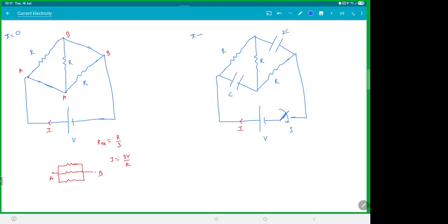If you wait till infinity, the capacitors will get full. Now be careful. There is a charge there. I don't know how much, so let it be Q2. This is minus Q2. I don't even know whether the charge is same, so I'll just take Q1 and minus Q1. Let the signs take care of it. The current in the capacitors will be zero. That much I know. So all the current will flow through this guy and this guy. Follow the red line. It doesn't pass through the capacitors.